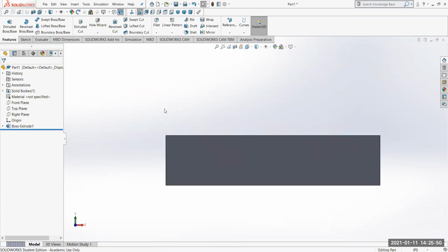piece here. We can either make it as a rounded top or make it as a square top and then use the fillet to round it over. Whatever you're comfortable with is acceptable. I think for this one, I'm just going to make it square and then round it over with the fillet command. So if I look at the drawing, it is 4 inches tall, and the width is 4 inches wide.